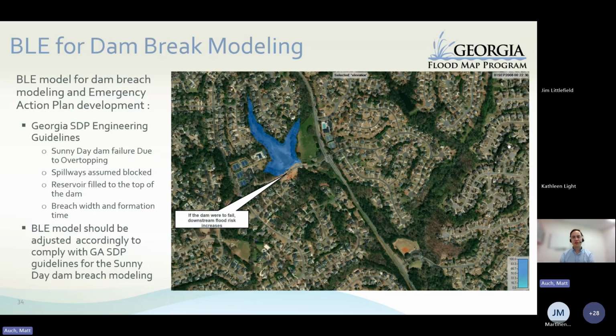If that dam falls within a certain criteria, then if it's deemed to be high hazard, they require an emergency action plan for the breach zone, so that in case, to mitigate the potential for loss of life. So you'll need to consult with the Safe Dams engineering guidelines to look at the specific regulations, and then ensure compliance with the standards for the breach and inundation modeling.